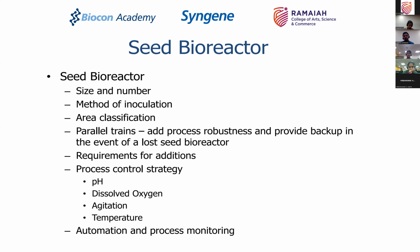Likewise, when you add an additional nutrient into the fermenter, if the agitation is not right and it does not get mixed up, there will be pockets within the fermenter where in some places you will have excessive nutrient available. On the other side, it is starved of the nutrient. In the starved region, the cells will start to die, and in the enriched section, it is unused media. So all these are important factors while designing a bioreactor.